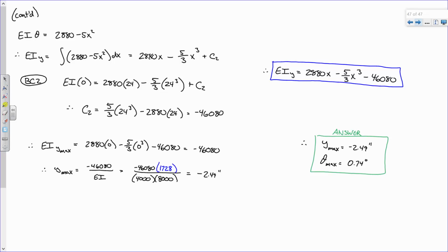I mean, you all are engineers, so I'm trying to run this out by you. There are two other options that we could do for this beam that may not be as apparent, but they are very possible. What's another option? Make it shorter. Now, you say change the length, and I think I spoiled it. Would you want to make it shorter or make it longer? You want to make it shorter. Making it longer is only going to make the deflection get even worse. Okay? So making the beam shorter will reduce your deflection. And maybe that's possible, maybe it's not. Okay? What's the other final option?